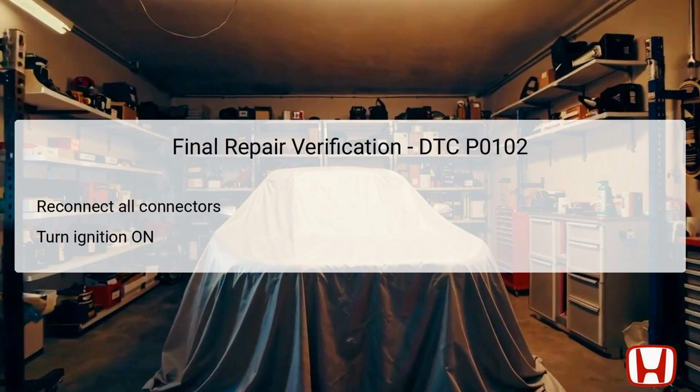If DTC P0102 is still indicated, this suggests that further investigations are necessary. In this case, focus on inspecting for any loose terminals or poor connections at the MAF sensor, IAT sensor, and ECM. If the ECM was updated or replaced during the course of troubleshooting, conduct another round of checks. Ensuring diligent verification will help confirm that no underlying issues remain.